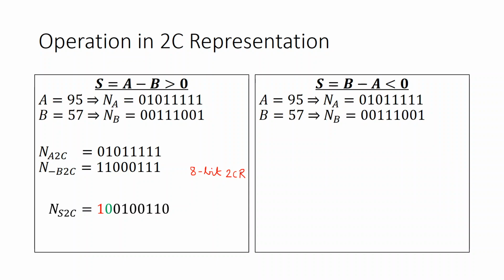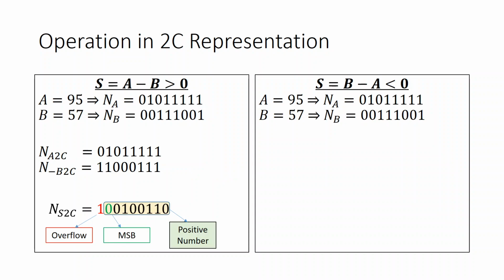Now if you do the addition, you keep on adding this, and you will see that this number comes out. This is simple arithmetic addition. I hope by now you are familiar with doing this. Now note that in this number the red marked one is the ninth digit coming up. So an additional bit is coming, and this additional bit is termed as the overflow bit.